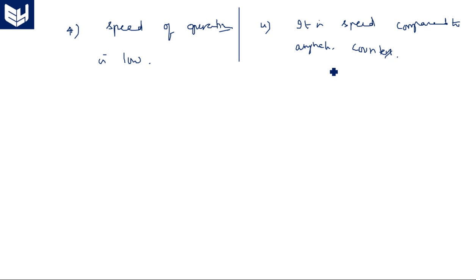Because, can you tell me, all flip-flops are activated at a time simultaneously whenever the clock pulse occurs. That means the propagation delay we can simply count with the propagation delay of the first one flip-flop.